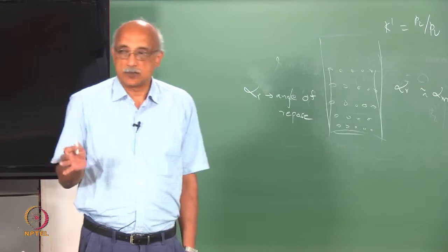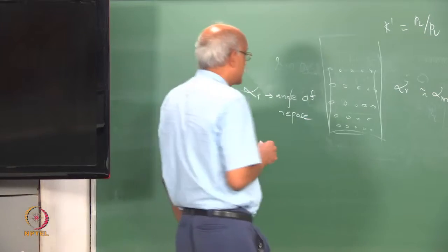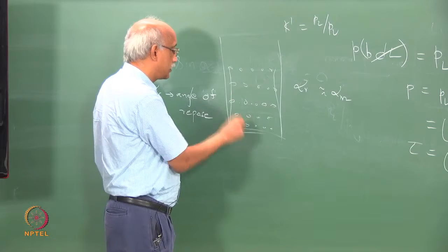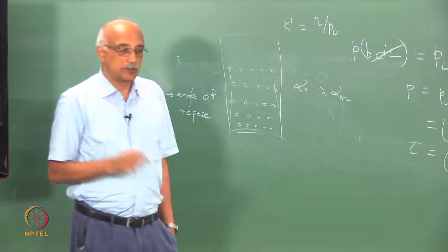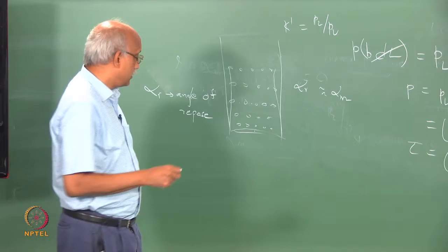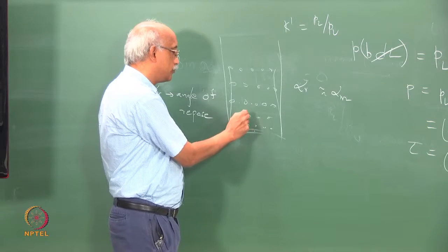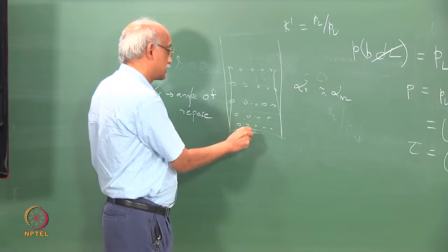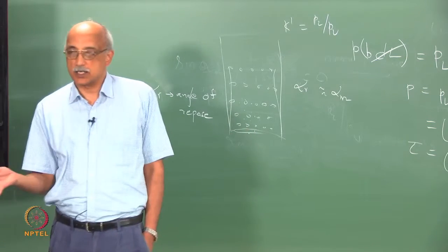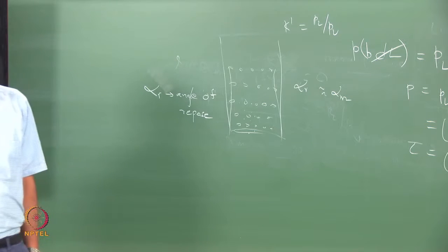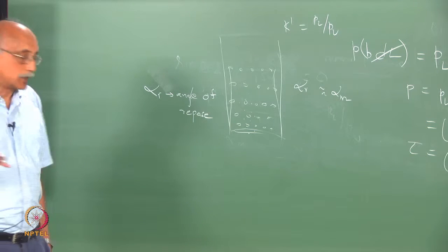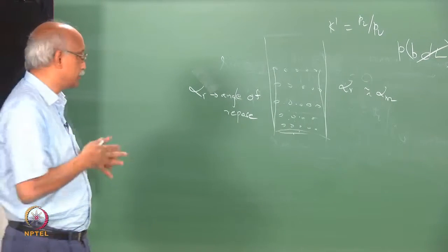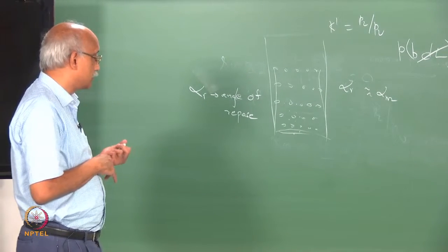In reality it almost never happens, and the reason for that is that when you look at how particles in a bulk behave versus particles near solid surfaces, the behavior is very different. For one thing, particles in the bulk have many more neighbor particles around them, whereas particles near the surfaces have only the surface on one side. So, the number of nearest particle neighbors is almost half for particles on the peripheries compared to particles in the bulk of the particulate material.